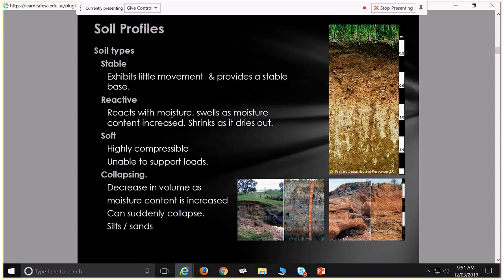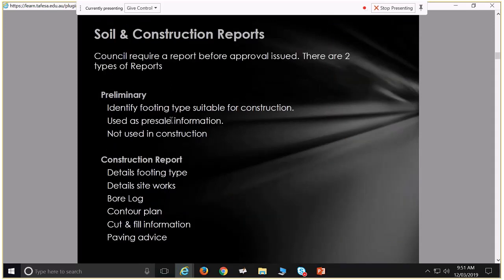If we give that a little bit of a shake and add some moisture to that, we can actually get that to take up less volume. Sand does exactly the same thing. So you've got your grains of sand with their irregular shapes. When you add moisture, that lubricates them and they fit together better, and then they don't provide that bearing to the footings, so they can collapse.